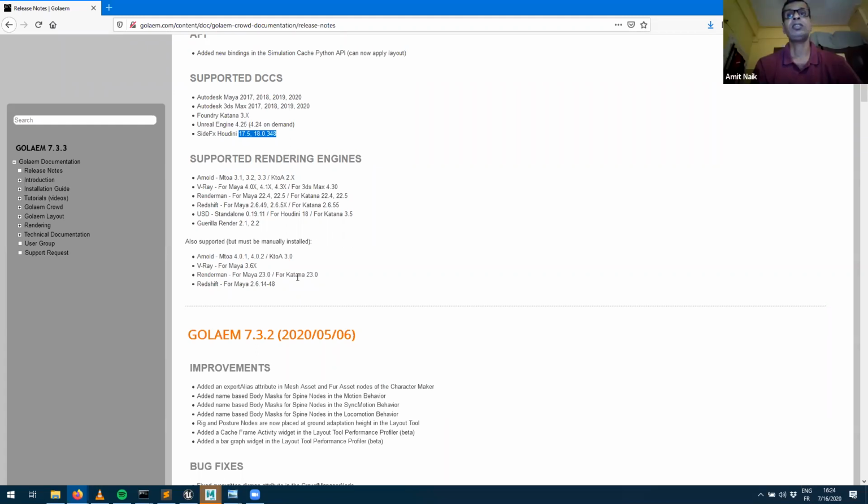The next one is, is it possible to add custom scripts? And I think that's the last. Does it support Python? So custom scripts, for sure, in plenty of ways. I can't really detail everything, but we have an API around almost everything. Let's say you don't want to open Maya and create a simulation from scratch, convert your characters and make caches. Without opening Maya, that's something you can do with Python easily, or you can even write some C++ code. We have a C++ API and a similar Python API.